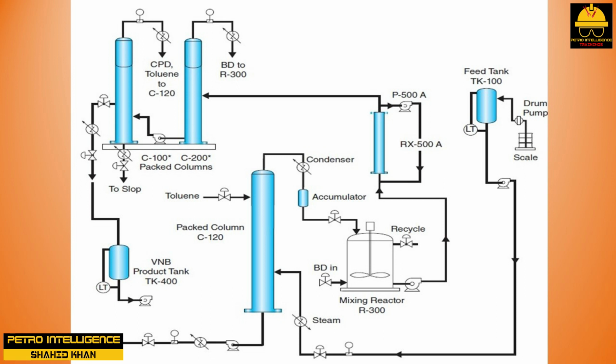In the continuous mixing reactor, chilled water coils maintain a low temperature. Butadiene enters the bottom of the reactor and mixes with the overhead distillate. The mixed feed is sent to a feed preheater before it enters the tubular reactor. The reactor resembles a shell and tube heat exchanger with 3 large tubes. The outer jacket is filled with hot oil that maintains a specific set point.